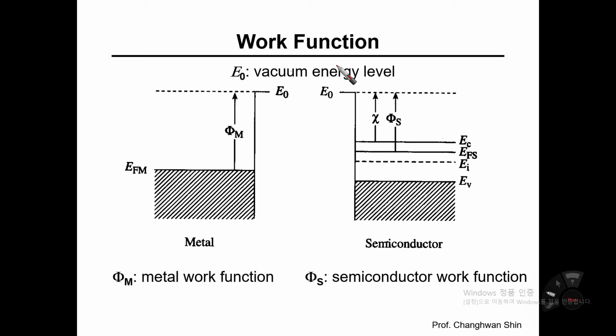So going back to the energy band diagram, you can draw your own energy band diagram for metal. A metal has no band gap energy, so energy states almost continuously exist. Of course, between two different energy states are very discrete, however it looks like there is no band gap. But a semiconductor has its own band gap energy, as illustrated here.